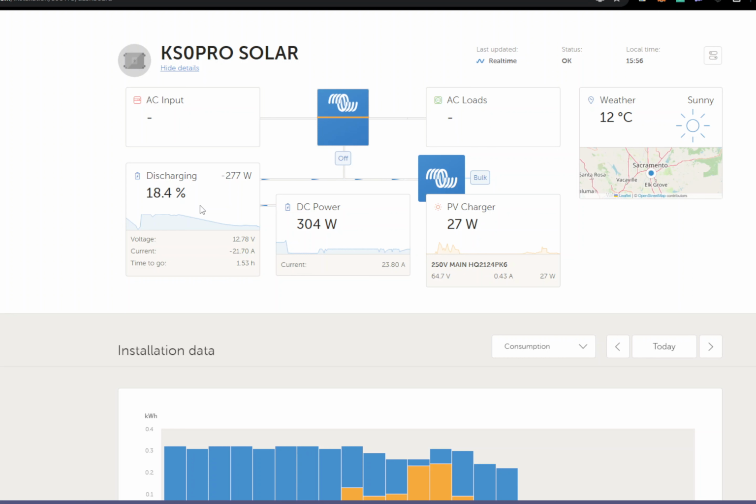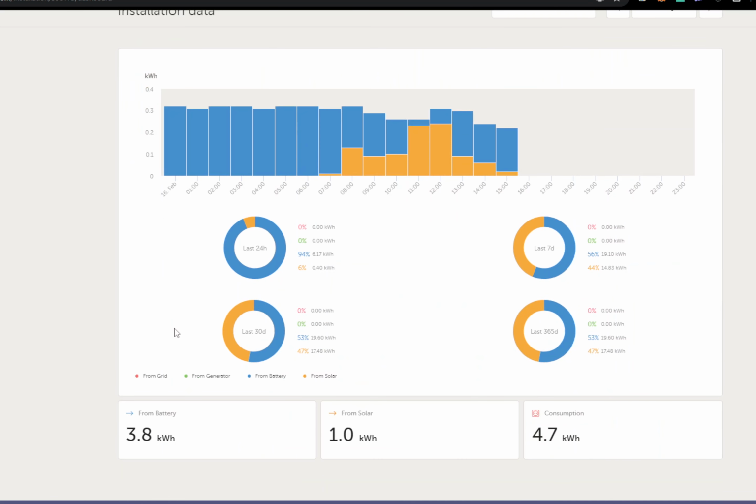You'll see on that video, it was 2 batteries totally charged. I was supposed to have a total of close to 5,000 watt hour battery, 5 kilowatt hours, and my system already used 4.7 and only 1 kilowatt solar support, so it will obviously not be enough to run this 24/7.